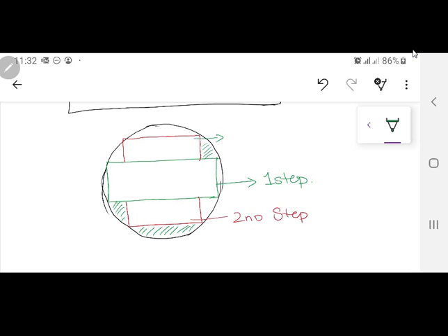Now the percentage fill area, let me give you an answer. If you are using a 2-step core, the fill area is approximately 64%. So only 36% is air gap. But if you are using a 3-step core, that value goes to 84%.